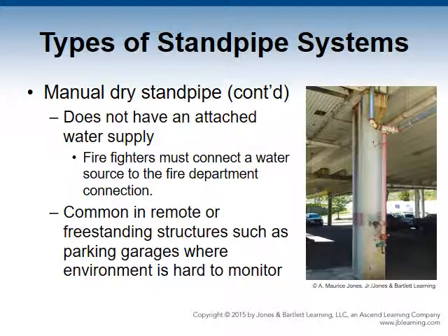Manual dry standpipe. This system does not have an attached water supply. The only thing in the pipe is atmospheric air. Firefighters must connect a water source to the fire department connection to use the standpipe. This system is common in remote or freestanding structures, such as parking garages, where environmental concerns and tampering are hard to monitor.